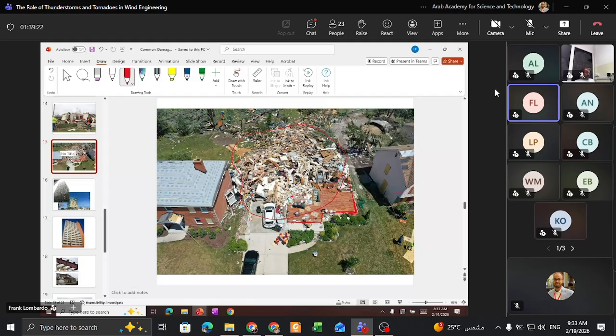On this particular building, because it is so interesting, we did an LES study where we tried to replicate the neighborhood as obstacles, and then ran a similar tornado through. What we did find was that there was an acceleration in wind speed in that general area. It doesn't prove it, but it was interesting that we noticed it around the same spot as we saw this damage.